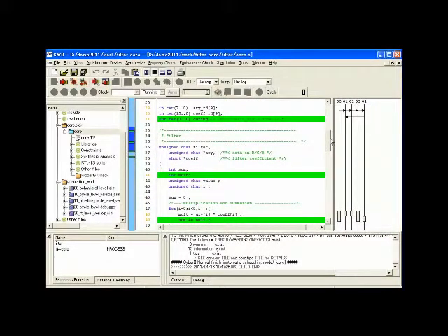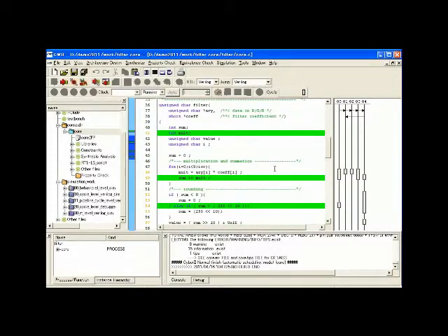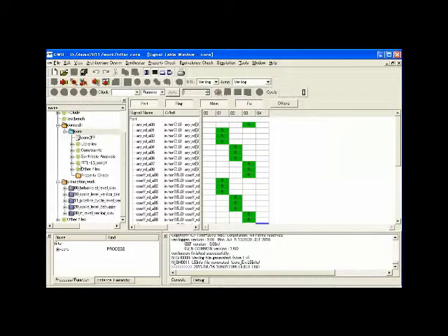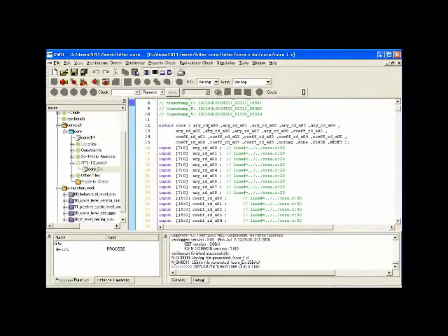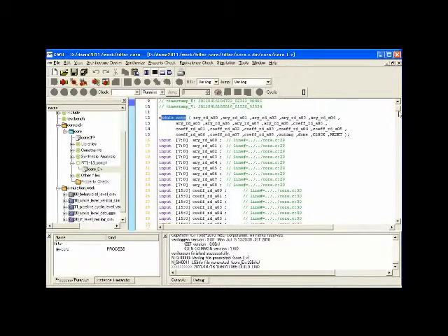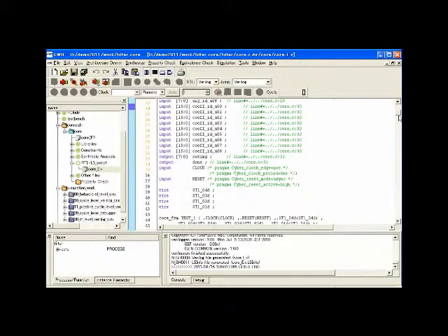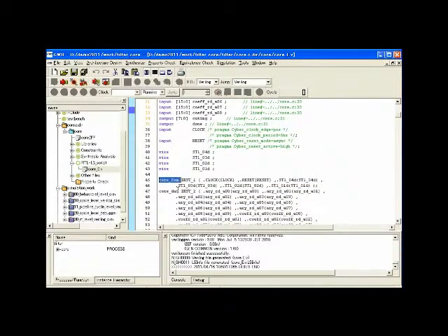Once we are ready with the results, we can proceed by generating the RTL for our C description. We choose Verilog or VHDL. In this case we will choose Verilog, and we proceed generating HDL. It finished, and it created the Verilog. We can see that the Verilog main module is named core, same as our process, and it created a finite state machine and a data path.